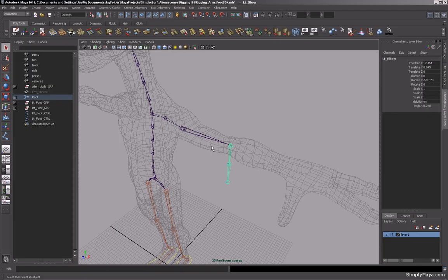So this is the preferred angle for the bend in the elbow. So our IK handle has something to sort of calculate, it has something to solve, you know, the bend, and it won't flip backwards and all that kind of thing. So then just simply set the rotation back to 0, and to check that that's worked, right click again, go assume preferred angle, and it should bend back to the sort of 60 degrees or whatever it was that you've just set. So that's all good to go.